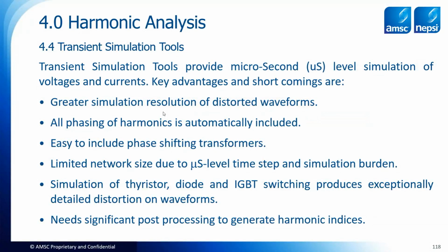All of that is automatically included. But you can only have a limited network size because it's simulating at such a fine level. You can't put 1,000 buses in here, or even 100. It's going to take hours just to get your simulation done. But it does let you simulate all the switching action of thyristors and diodes and IGBTs with exceptional detail.